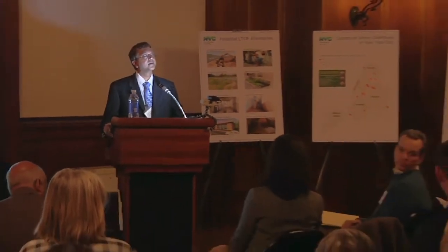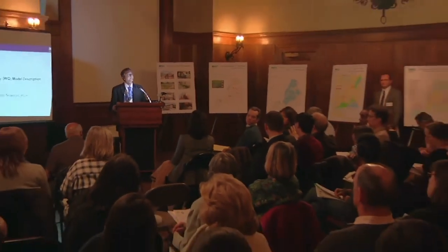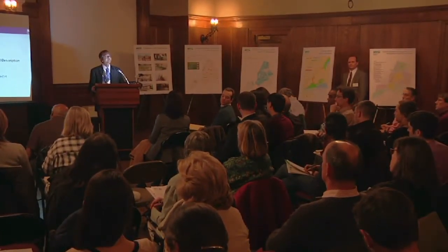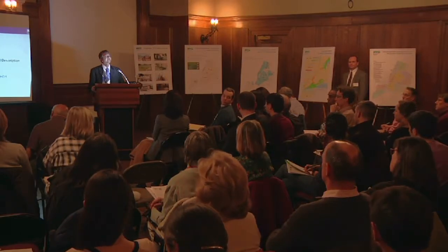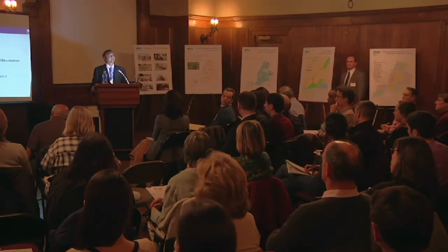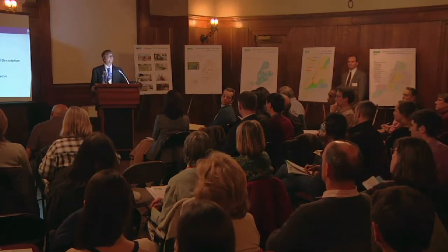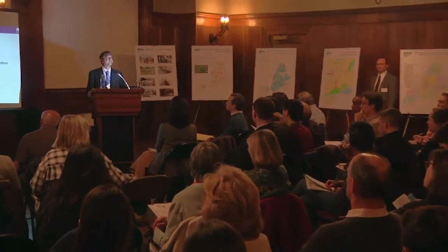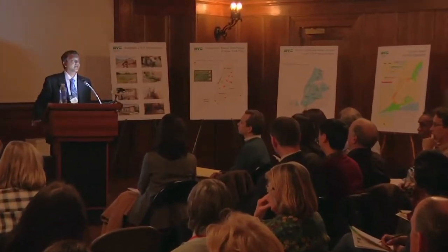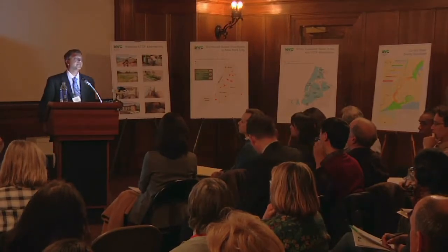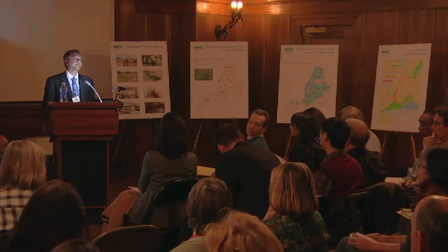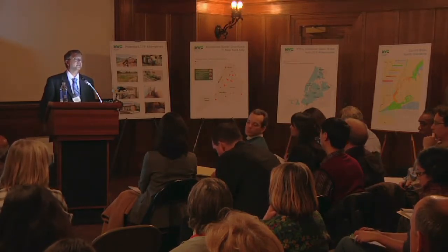But it seems like you already have the data for this. You're getting creative differentiation from your prediction as you start to get higher volume flows. And if the systems behave like all other flow systems, you would expect that your coefficients of discharge will change both for your pervious and impervious zones as you start to get higher flows. So you should be able to resolve your model potentially from, if you have the large storms characterized according to size, you should be able to get better resolution just simply taking the scale of impact and the volume flux, which is already in your model, already plugged in, right?